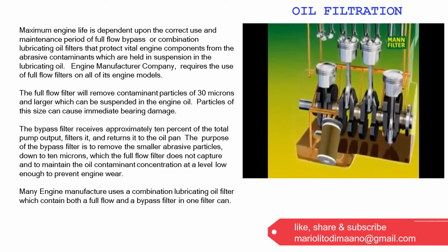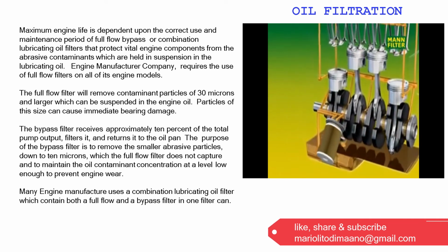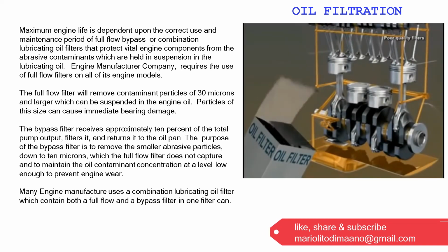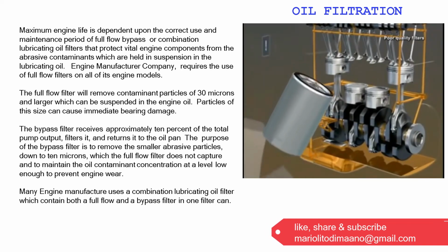However, with the constant buildup of dirt and chemical aging of the oil, it's essential to change both the oil and the oil filter together on a regular basis.